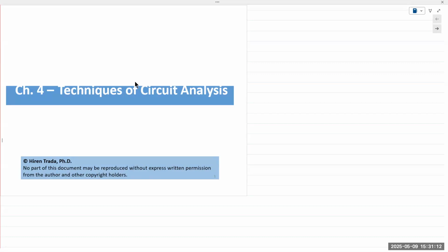But the only three equations or laws we need are, what do we need? That's it. Those are the only three we need. Everything else is based on these three: Ohm's law, KCL, KVL. And that's why we had individual homework for all of those topics. From Ohm's law, we already saw two other shortcut techniques, voltage division and current division. We also determined how we could add up resistors in series and in parallel. All of those were based on Ohm's law and then KCL and KVL.